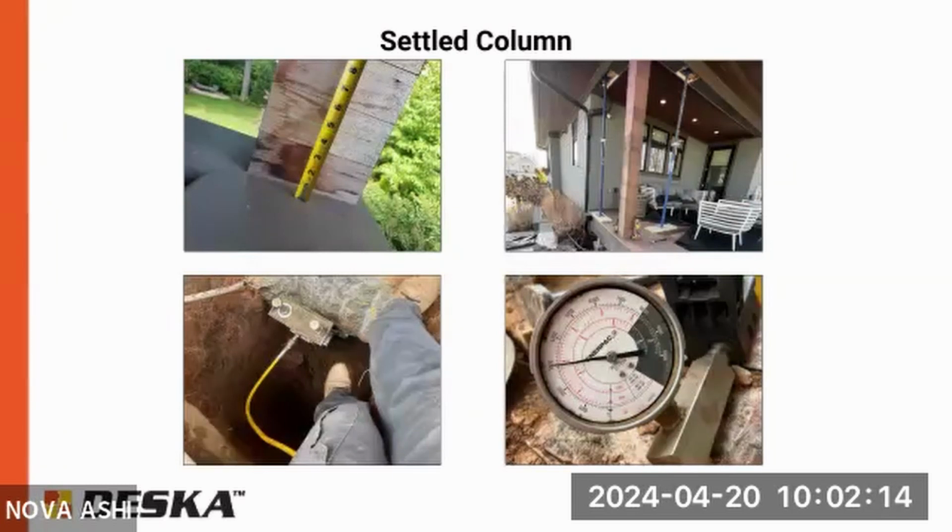Push piers are probably going to be too light to install, because they rely on the weight of the structure to push them into the ground. But helical piers would typically be the recommended solution. But it can be pretty expensive to do that too. So.